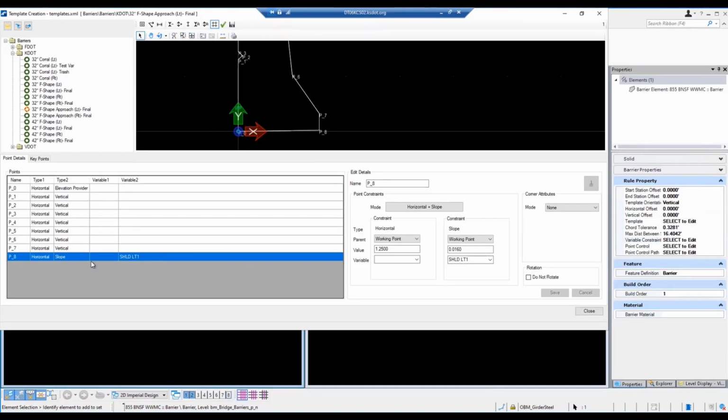If I can briefly go through this, 0.8, I'm going to apply shoulder left 1, that's what I named it. The bridge rails don't let you apply the super elevation automatically. There's no super elevation checkbox here. But you can go in and define whatever your shoulder slope is. You can define that for the bottom of your slab, or bottom of your bridge rail. So 0.8 will rise or fall based on that slope.